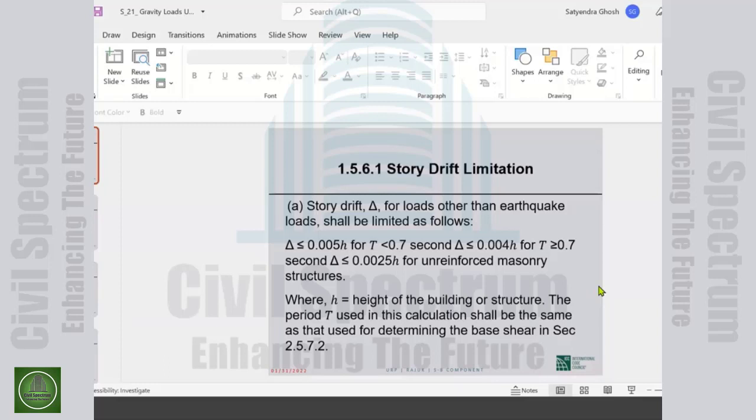A lot of the questions are related to the quiz. Kindly mail them to the support. Let me explain the period. Although the earthquake period is being used, that is a little bit strange, but not by much. The idea is that a period less than 0.7 of a second is supposed to be rigid buildings, and the other ones are more flexible buildings, with a longer period.